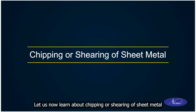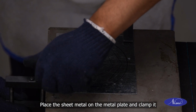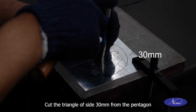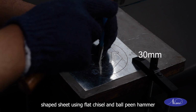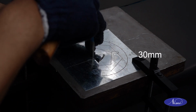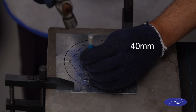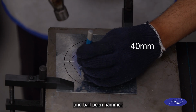Let us now learn about chipping or shearing of sheet metal. Place the sheet metal on a metal plate and clamp it. Cut the triangle of side 30 mm from the pentagon-shaped sheet using flat chisel and ball-peen hammer. Cut the pentagon of side 40 mm from the hexagon-shaped sheet using flat chisel and ball-peen hammer.